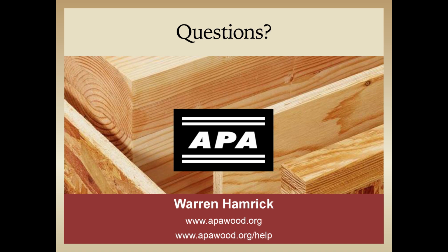Sure. So this performance increase is referring to the wall plates, and they're in compression. So just a little background, wood is weakest when load's applied perpendicular to the grain. If you think about that wall being loaded vertically, so obviously it's being loaded from the top of the wall, the wall plates directly under the stud ends are being compressed perpendicular to the grain. And there's slightly more area of a sill plate when you go to the 2x6s. So you've got a 2x6 sill plate versus a 2x4, and because there's slightly more area, it performs about 5% better under this load condition.